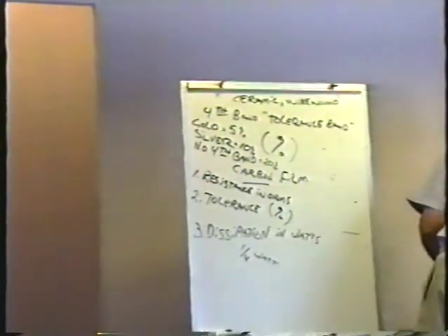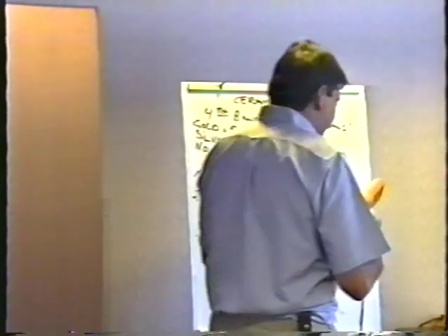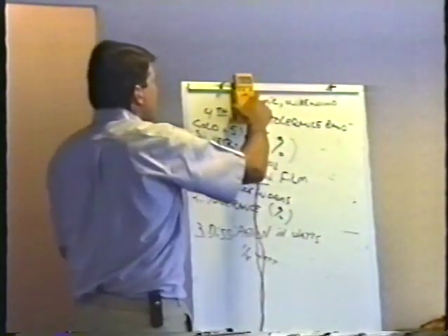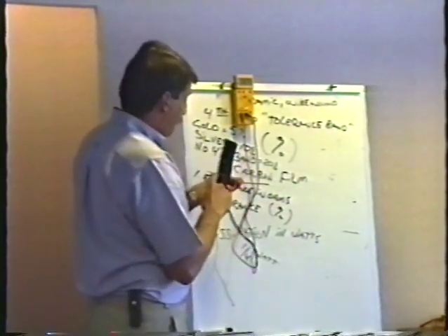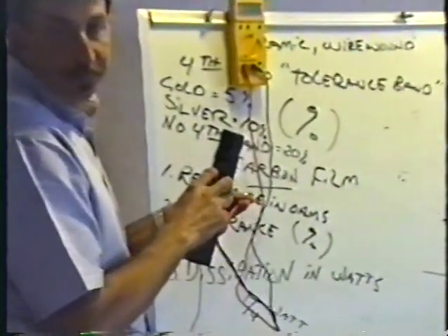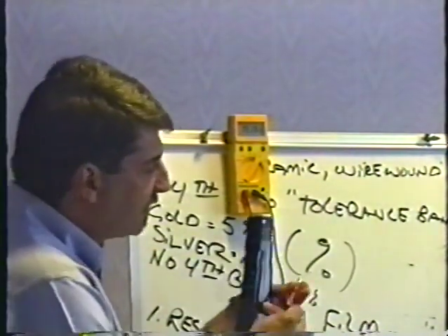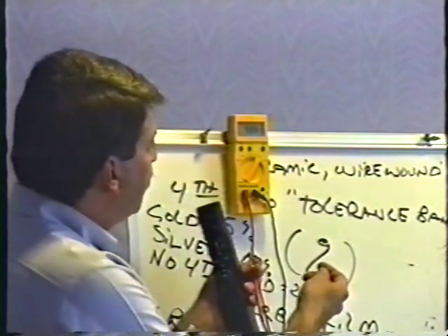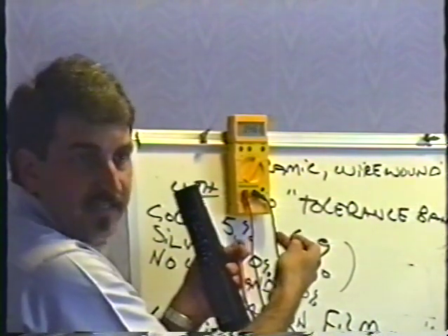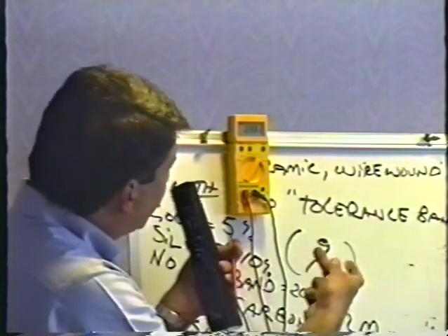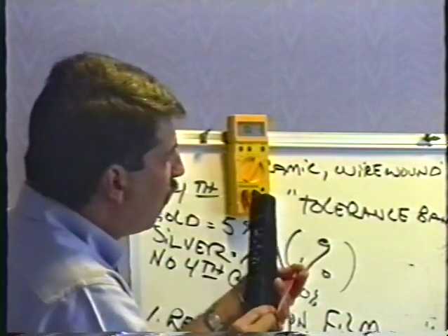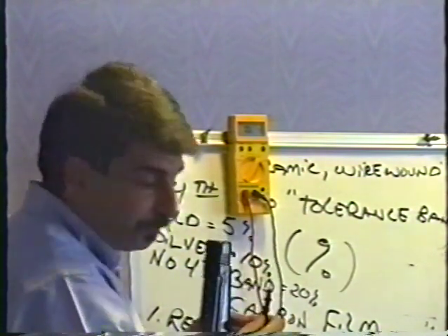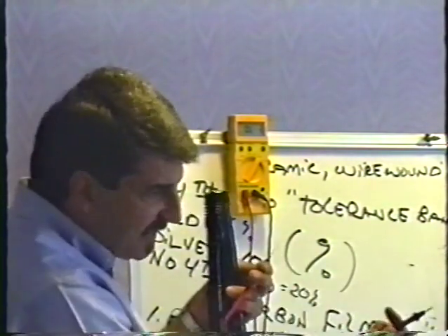When you measure the resistor with your meter, you should not put both hands on the meter leads, because your body resistance will affect the reading. In other words, if I put my meter leads across, let's say if I just put my hands on the meter leads, you can see the meter's, well, maybe you can't see it, but the meter's doing something. It's freaking out because of my body resistance. So when I check a resistor, I can put one hand on the resistor, no problem. But my body's out of the circuit now, isn't it?